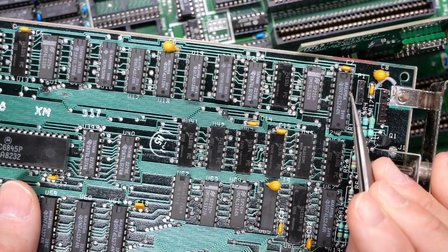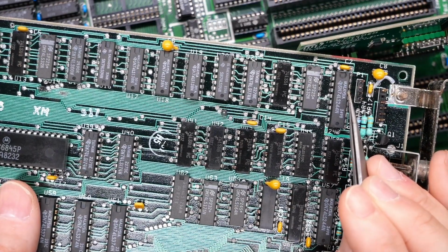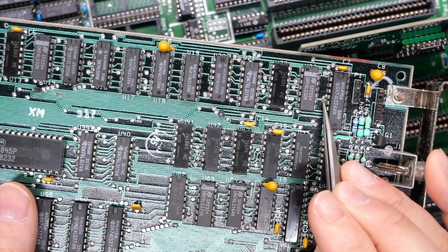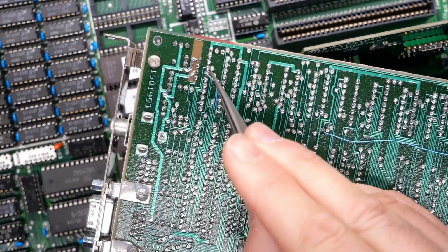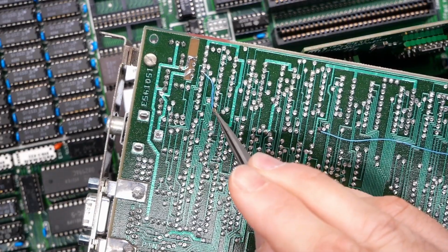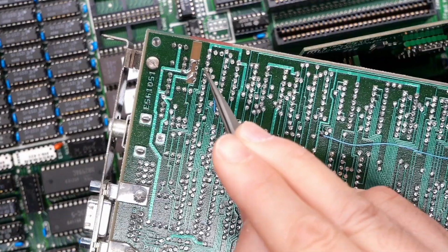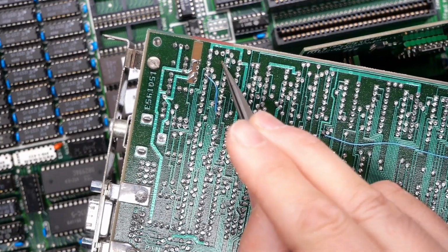Okay, here's the 244, it's pin 4. That is the input for that register or that status bit. And it's this trace right here. So I just cut through there. And on the back side, I permanently grounded the input to that pin right to ground here. And it's okay, you don't need to use a resistor for this kind of thing. Grounding inputs to these types of chips is totally fine.